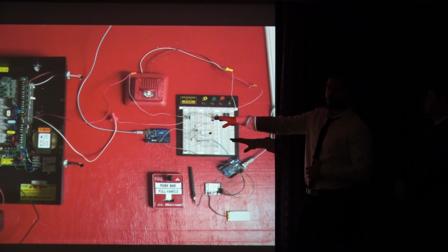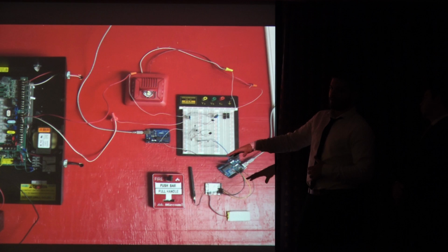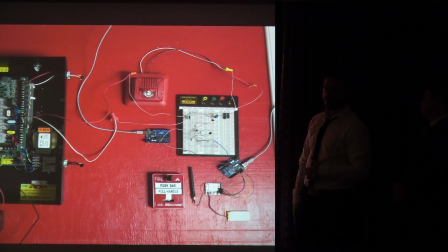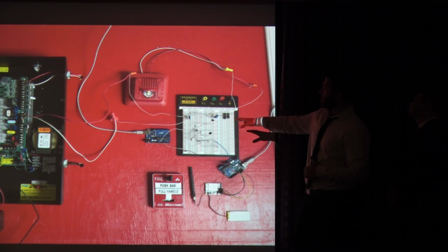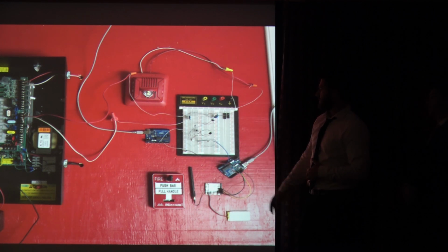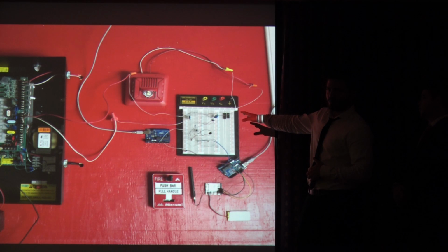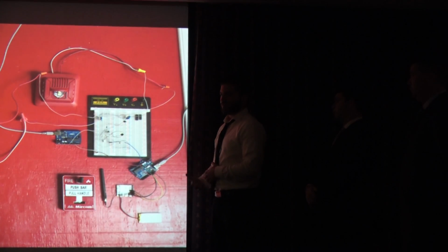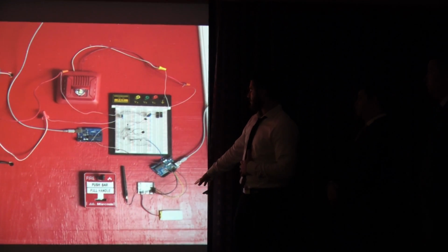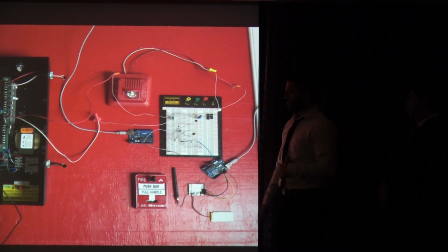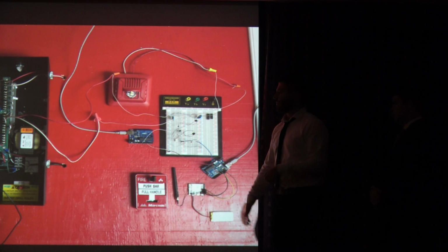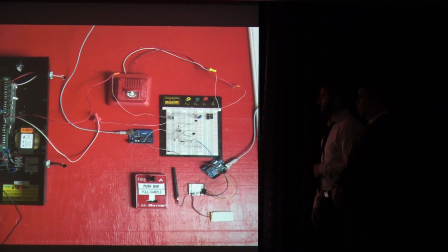The fire panel goes from a 1 volt output standby phase to a 28 volt rise. The most important part of this setup is our detection circuit, which takes this 28 volt rise and makes it easier for our Arduino boards to be able to read it and display the signal to our GSM and our gateway board. Then we'll be going over the technicalities.